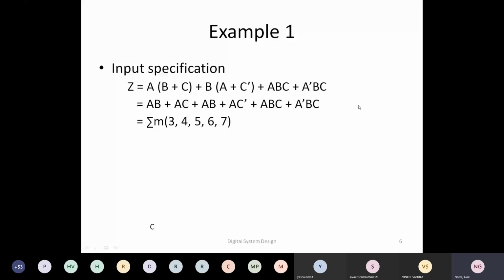So we will expand them, and this will become a canonical form, which we also know as sum of min terms or product of max terms. This canonical form provides a very good way to describe a function. One function cannot have 2 canonical forms, it has to be only 1 canonical form.